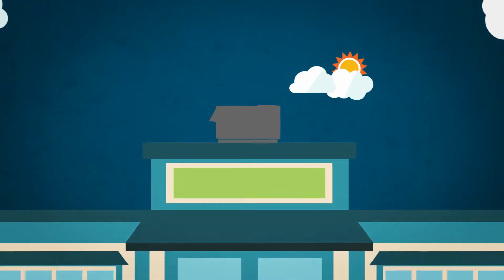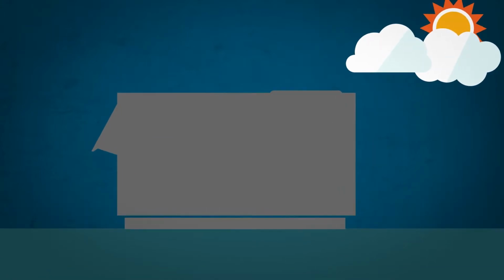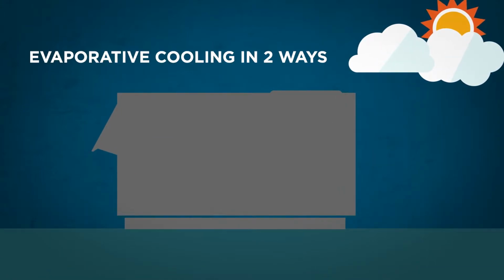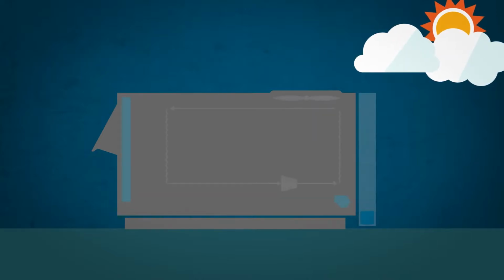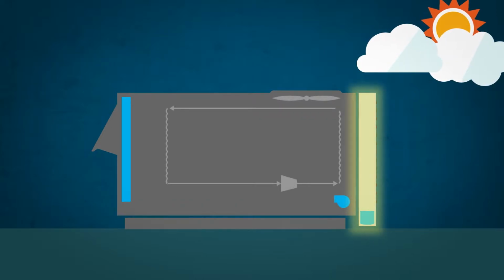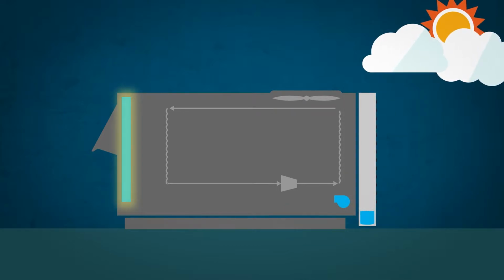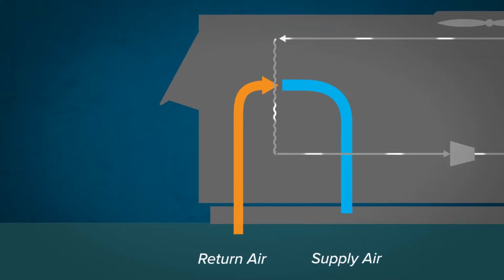Designed as a retrofit for existing commercial rooftop air conditioners, DualCool uses evaporative cooling in two different ways, hence the name DualCool. Number one, it improves the efficiency of the vapor compression cycle, and two, it reduces the ventilation cooling load. Let's explain that a little further.